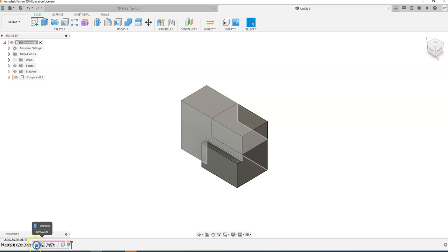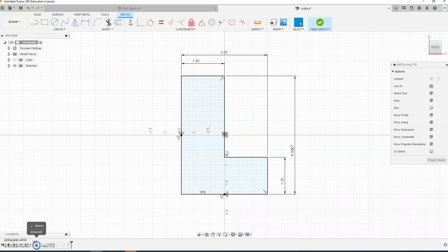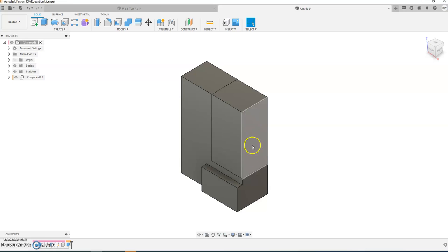Now what this does for you is, by doing it this way, oh no, our design changed. Yeah, messed up again. Let's go in here. That wasn't supposed to be 2 inches tall. That was supposed to be 4 inches tall. So change that to 4 inches, come back here, and notice how it automatically changes this other part that was linked to it to 4 inches tall.